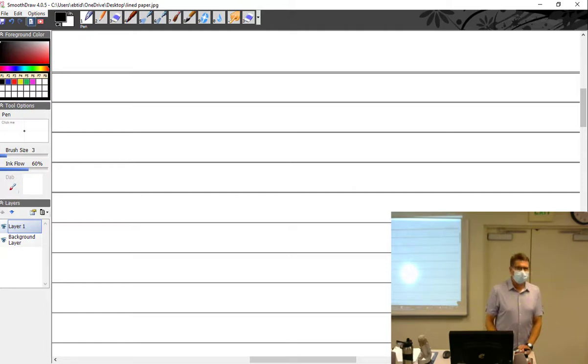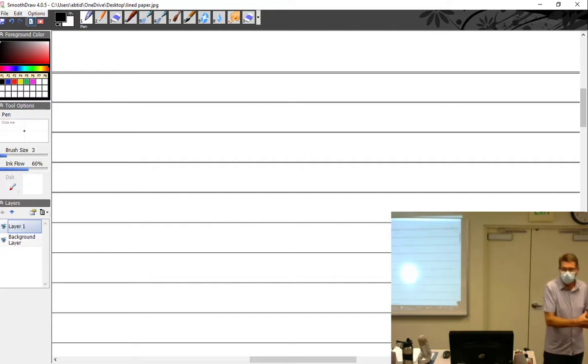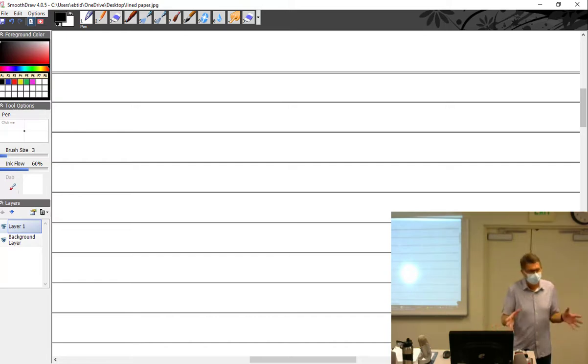Now, I say that, but you also have to understand that I have a Continental O-470, and there's a Continental O-470 manual, and there's a Continental O-470 operator's book. There's also the Cessna 182 manual and the Cessna 182 book. This is confusing, but if the Continental operator's manual for my O-470 said my red line is 2700, and my book for my Cessna says it's 2400, who wins? The Continental manual. Oh, no. The Cessna manual, because that's the application. That's how it was certified. Cessna went out, they bought that engine, they bolted it to this airframe, they wrote that book. It takes precedence over everything.